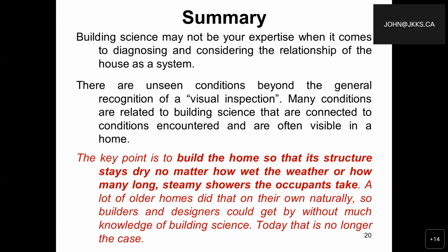Where do the air leaks occur? Similarly, pockets of moisture or wetness in a building envelope can be identified so the source and extent of the problem can be addressed. We saw that in cases up in the attic, or in those photographs where a little bit of insulation was removed because people were concerned about issues such as mold developing on their drywall.